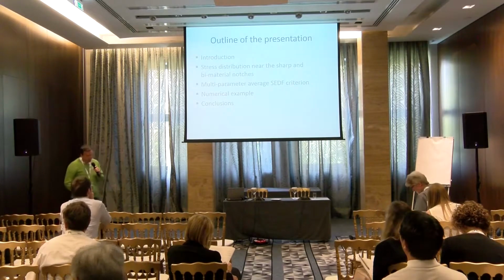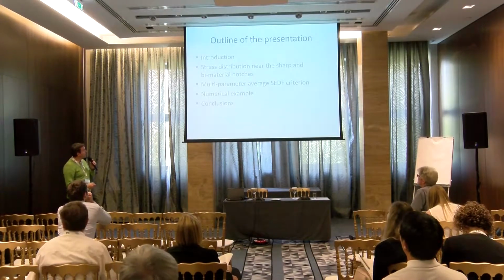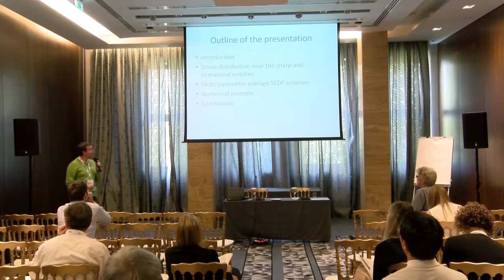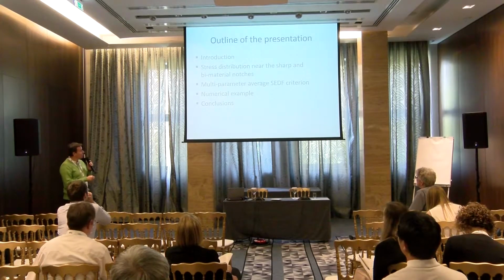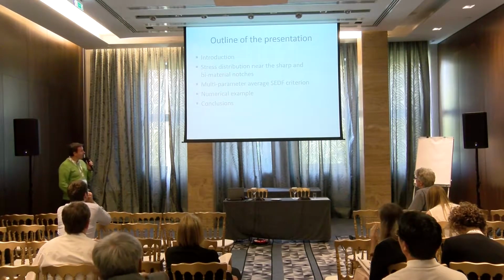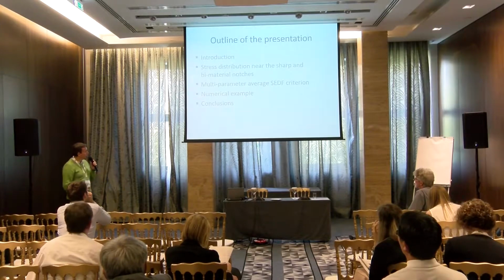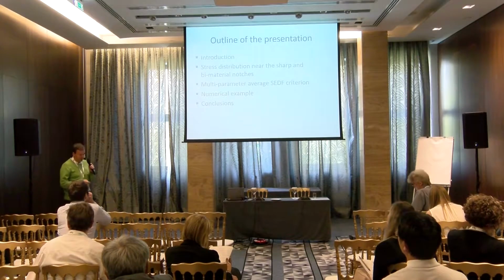So first, the outline of the presentation. After short introduction, I will talk about stress distribution near sharp and bimaterial notches. Then I will introduce multi-parameter average strain energy density factor criterion. I will show the application on numerical example and final conclusions.